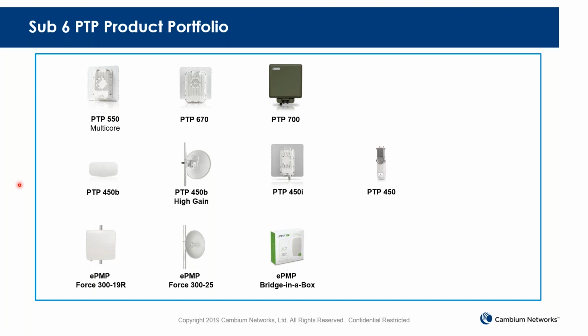You need to balance the return. High performance antenna really means the slope will be cut further. In the licensed microwave, we have class 2, class 3, depending on which, in the ETSI and the FCC. In the ETSI, there is class 2, class 3, class 4. The higher the class, the better the antenna.